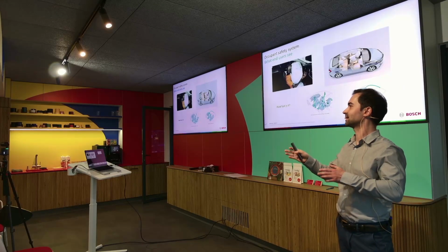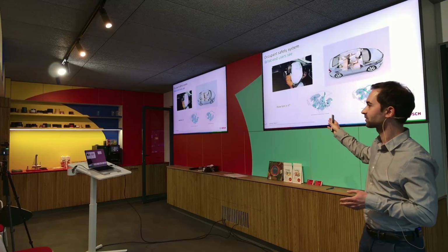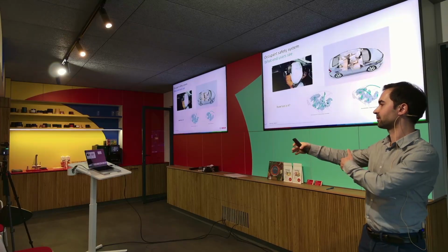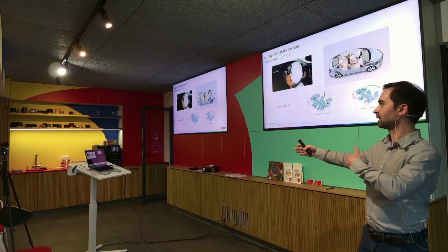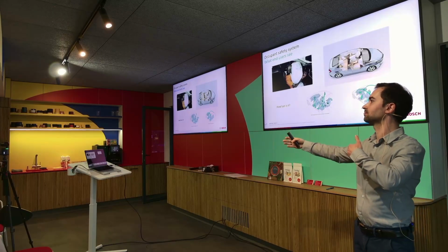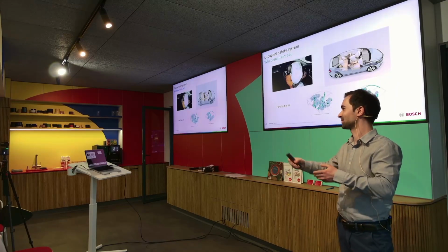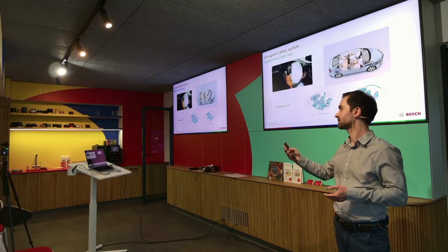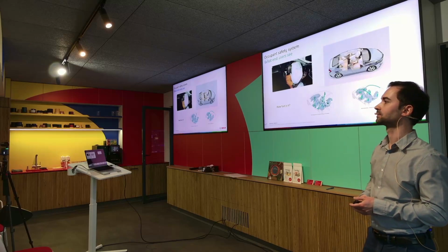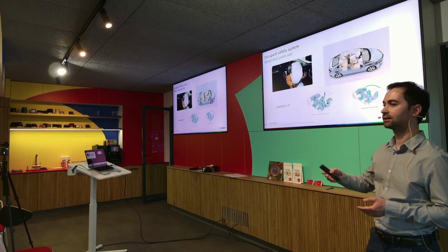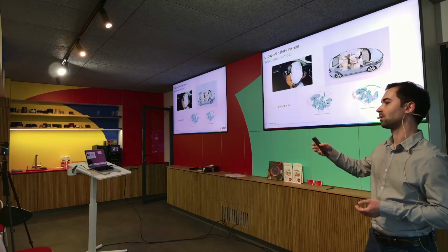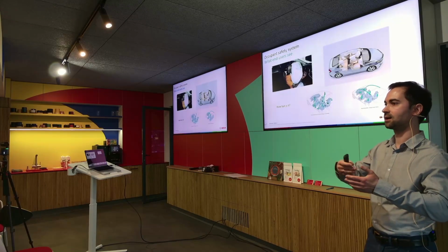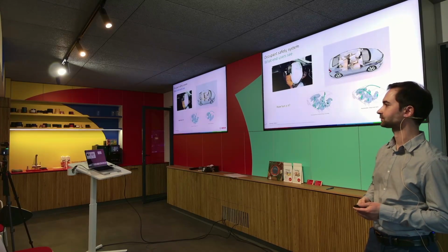I would rather say 10 milliseconds in case of front crashes, but in a front crash you have a big deformation zone, and that lasts for a lot of time. So yes, you have time. In case of side crashes, for instance, 5-6 milliseconds is a totally normal time for making the decision, and then after 10 more milliseconds or something like that, the airbags are fully inflated.